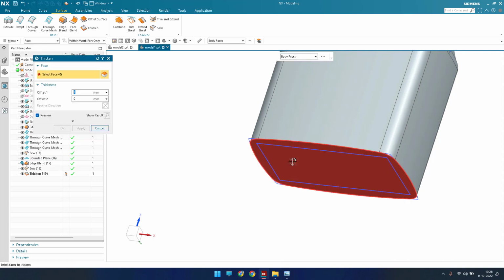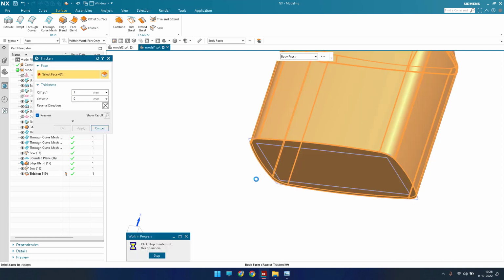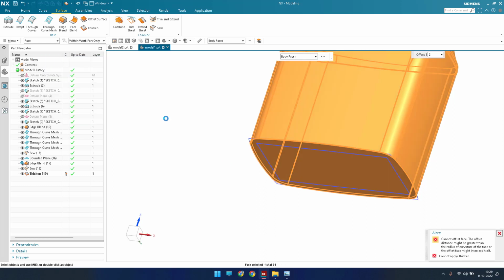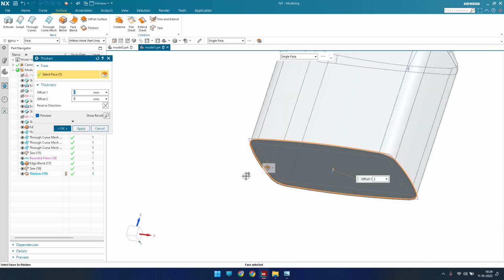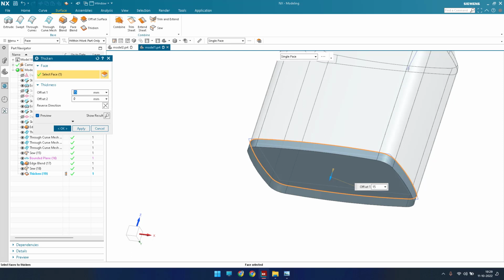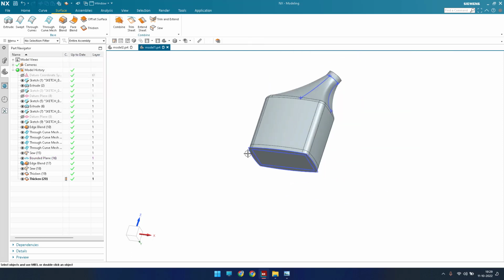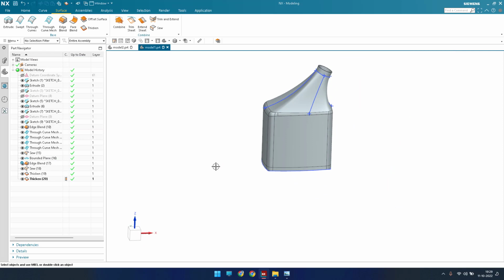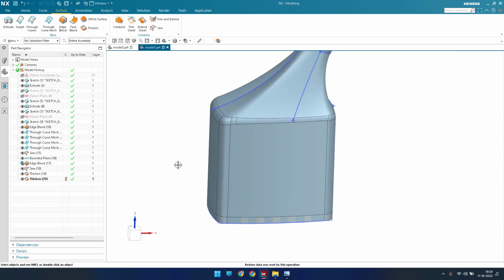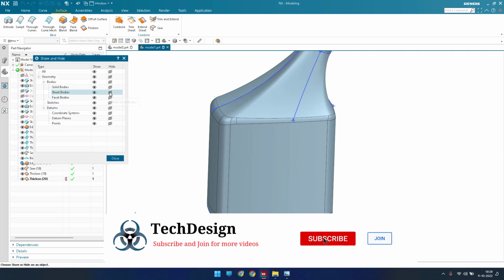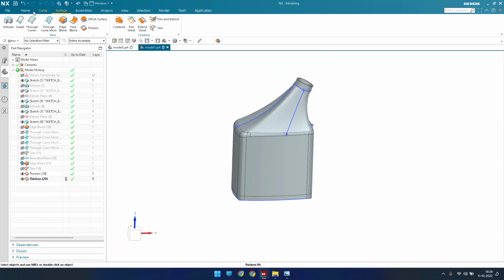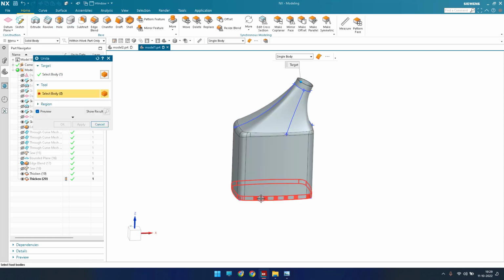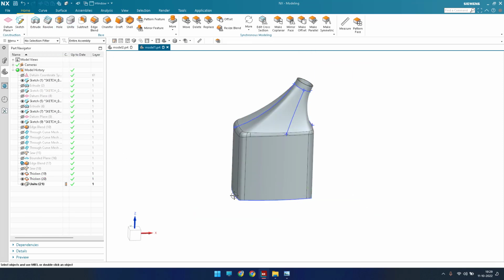Now again go to thickness, and you can select a single face, the bottom face. This is 15 mm and it should be inside. You can just click OK. Now all the sides are done. We can just hit Ctrl W and switch off this sheet, and you can see this is a different body and this is a different body. So we can just go to unite. Unite these two. Okay, now it is united.